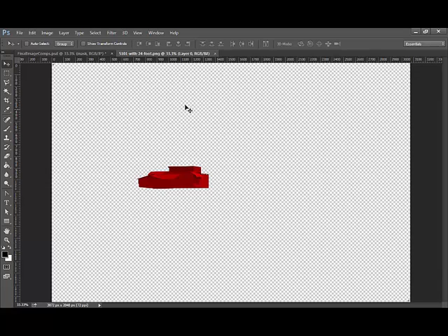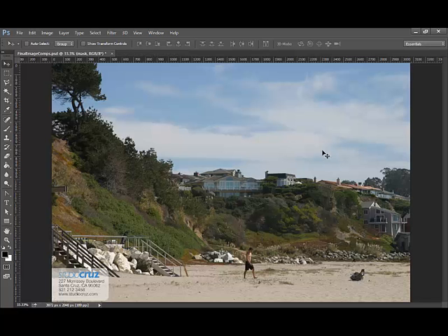So here is another rendering, this time from the 5101 camera, showing the 24-foot proposed extension to the existing property, and it's been saved as a PNG file with transparency. This allows us to trim it more easily in Photoshop, as we'll see in a moment. And there are two little dots in the corner to make sure that the entire frame is selected and pasted correctly into Photoshop. So I'll hit Control A, Control C to copy, Control W to close, Control V to paste, and we have the target property in the correct location and elevation in position as viewed from the beach.